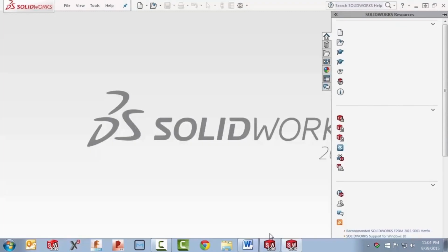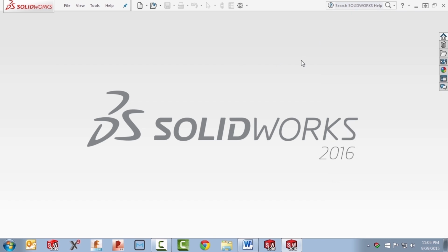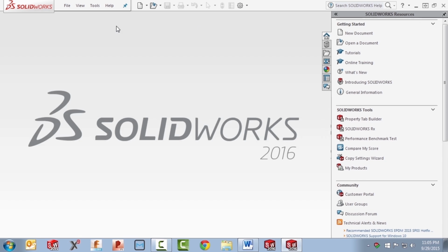Once SolidWorks loads, by default, you'll notice on the right-hand side various resources for you. This is the task pane, and it has a lot of functionality built into it. By default, this will show every time you open SolidWorks, and when you click anywhere on your screen, it'll minimize. If you expand this again, you can pin it open and leave your modeling window just to the left of it. This is not automatically locked to the right-hand side of the screen. You can move this around if you wish, but by default, it will stay on the right side of your screen.